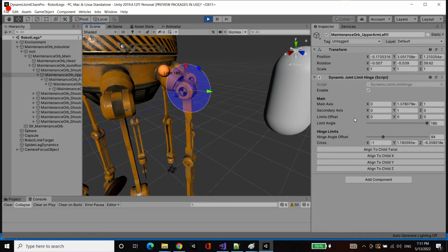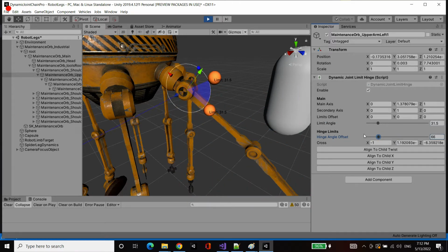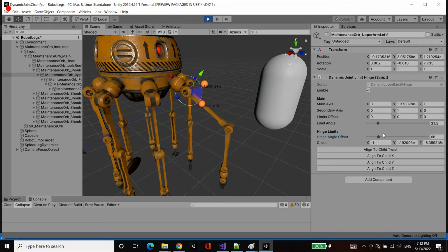Now, what I'm going to do is play around with the joint limit here. So if I change that limit angle, you'll see as the bounds reach a certain point, and I could change the offset as well, then the particles react with it while still going through the dynamic simulation and having forces and gravity apply, and while preserving that weight shift and change of momentum, but at the same time interacting with those boundaries or the joint limits, as you could see.